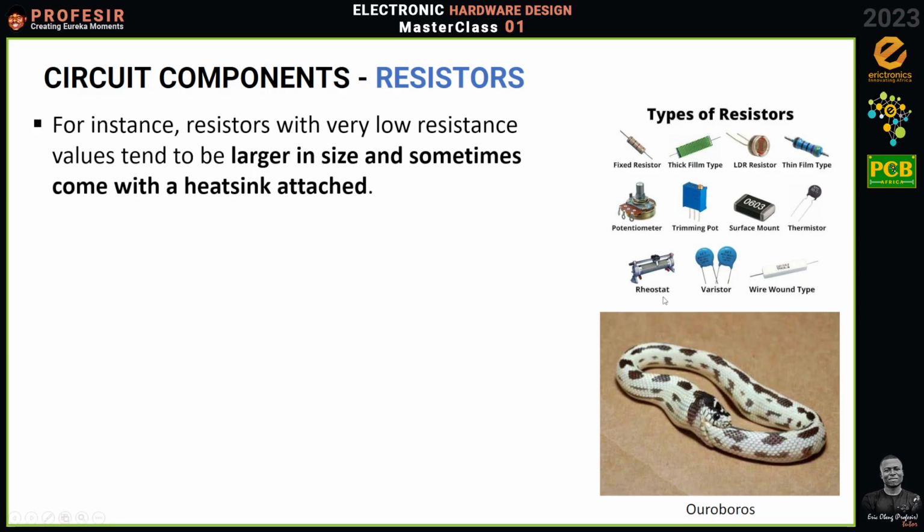Okay, good. Now, this resistor that you see here, we call it the power resistor or cement type. Usually, if you see big resistors like this, they will have very small value, because the smaller the value, the higher the wattage it has to deal with. These kinds of resistors that are used for very high current and low resistance, we call them shunt resistors.